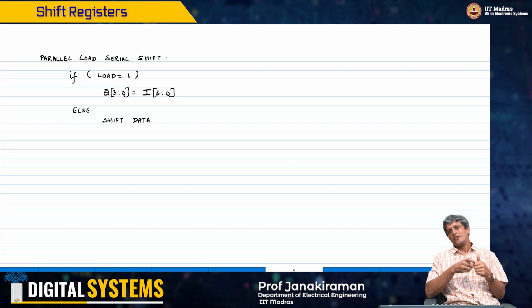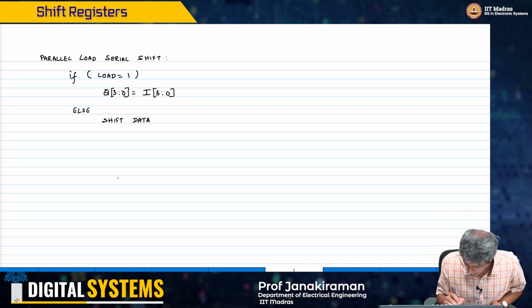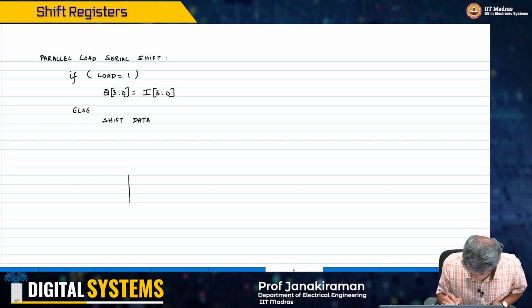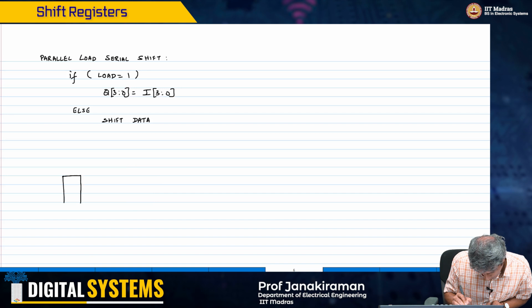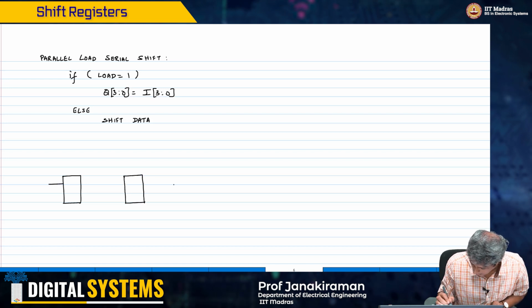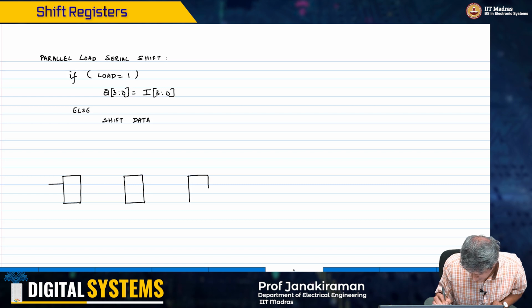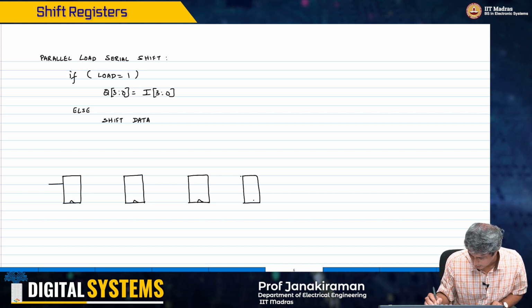Okay, so obviously, like I said again, the moment you have an if condition in your pseudo code or the algorithm, the simplest way to do this is to actually implement it with a multiplexer, right. So therefore I'll consider this, okay, and this is D0, D1, right, clocks are here.